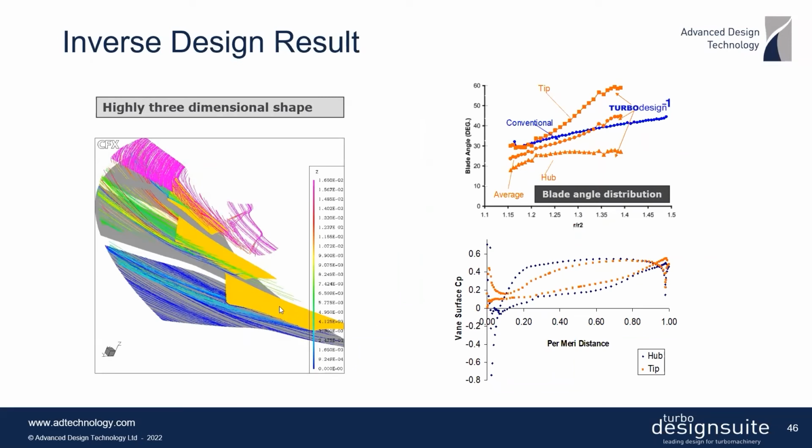What you can see clearly is that we have removed the corner separation. To understand why the corner separation goes away, it's a similar mechanism to what we saw in the pump webinar. You create strong span-wise secondary flows that move the low momentum fluid away from the end wall. We are also reducing the amount of positive pressure gradient here. A combination of these two helps eliminate this corner separation.